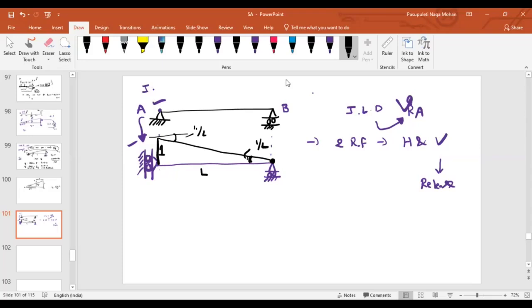Sir, is it necessary to point out the slope at any particular point? Is it helping us to find the reaction? See, if the load P is acting at a distance of x from A, can you tell me what the reaction at A is? Looking at this diagram, if you do not represent the slope, you know only this ordinate is 1 and this point is 0. What about in between? How are you going to find out?